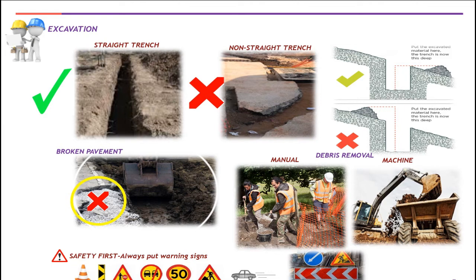Always secure any exposed existing plants in the field. Clean all entrances going to the building at all times to avoid complaints from the owner. The bottom of the trench must always be smooth to avoid damage to the duct later on. Where the bottom is rocky, a 10 cm layer of compactable bedding material is always recommended. Lastly, always maintain safety precautions on site from time to time.